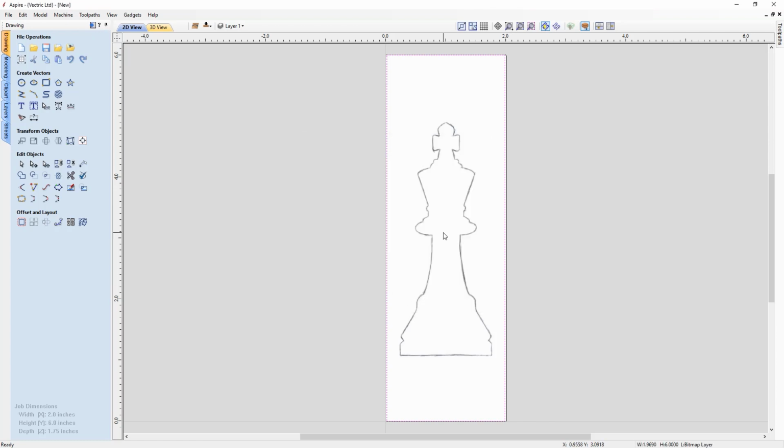Now the trick here is to draw only what we need. So we're only going to draw half of our cross, and then we're going to flip it over and then connect the two vectors together to make the full shape of the cross. Now with the cross, we're going to use our shape creation tool to create the cross, and then when we actually draw the half of our chess piece here, the body of it, we are going to use our turn function to turn that over, almost like on a lathe, where we're going to take a vector and we're going to spin it across the common center point or the common plane that our start point and end point share to give us that full rounded shape. And we'll take a look at that in just a second.